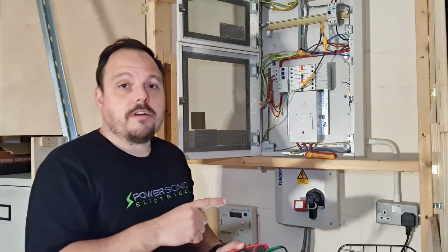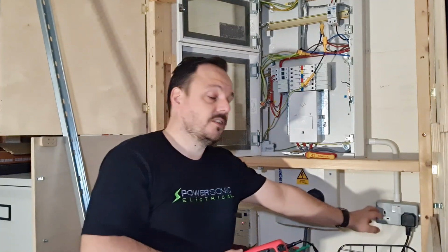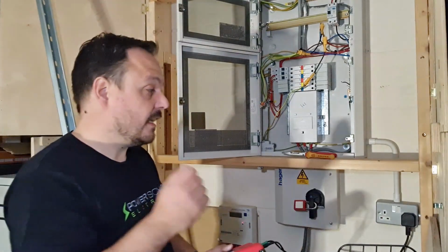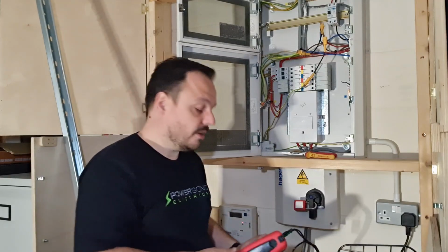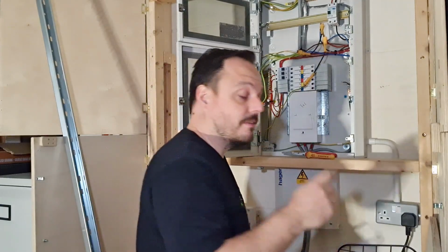One thing to do with your R1, R2, it's always worth checking at both sides because you can get high impedance points through your socket fronts, especially on older ones. So at that stage I'd be checking both sides as well, just to make sure you've not got an issue there on the socket front. But yeah, I'll spin you around now. We'll get set up for the lighting test and I will show you at the sockets for the other R1, R2. It's going to be a bit shaky camera work, but I'll try my best.